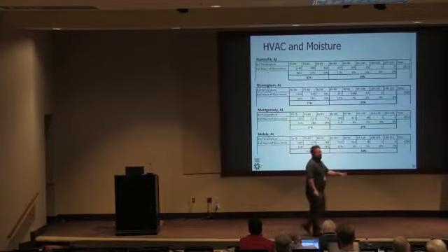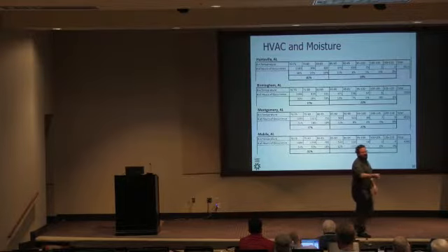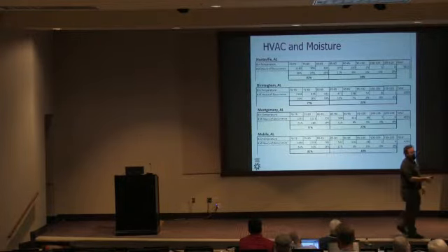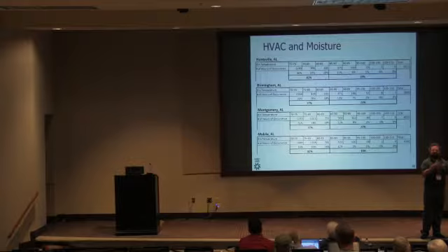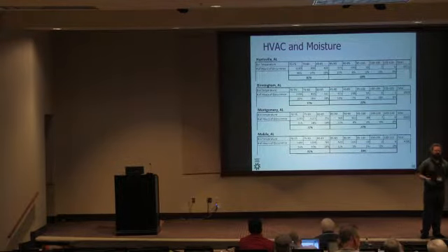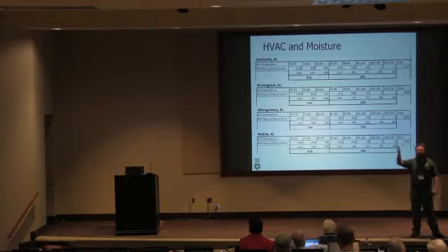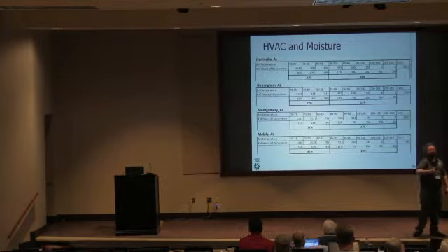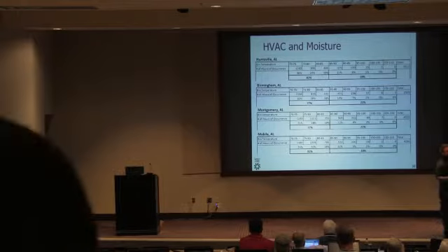But then every other day of the year, we can stage down the equipment, we can stage down the blower, and we can run to meet that actual load that's on the house. So the best case scenario really is, fine, oversize your equipment, but put in variable capacity and variable stage blowers so that you can meet the load in that house at any actual condition. And then you're going to get the best possible comfort.